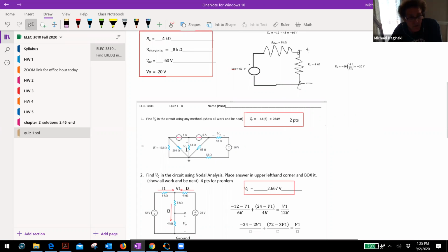Well, how much current's going through that resistor? 1 milliamp's going this way. 5 milliamps is going this way. How much is coming up? 6 milliamps. 6 milliamps, right? Times 44, or I'm sorry, 6 amps, pardon me, times 44 ohms, right? That's the voltage drop, right? Yes. So it's 264 volts, but what?